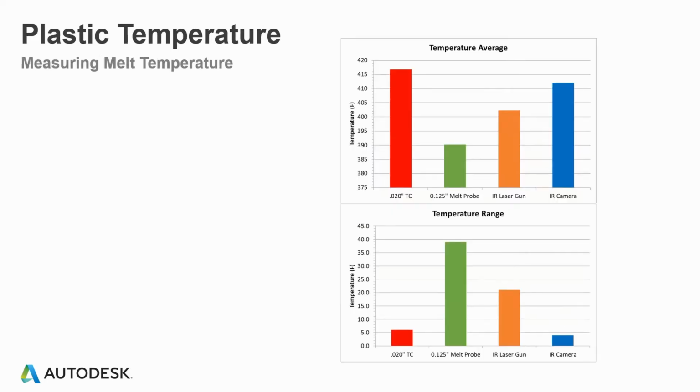Here we have measuring the melt temperature. So this is really coming from the Moldflow side. I've had a lot of discussions back and forth in these meetings and exchanging this information where we would always provide a melt temperature back and forth. Wanted to draw that to everyone's attention. How you take the melt temperature can have a significant influence over the reading that you get, which you end up telling the analyst the melt temperature was versus what it really was.